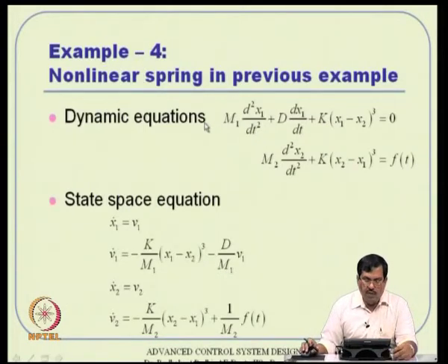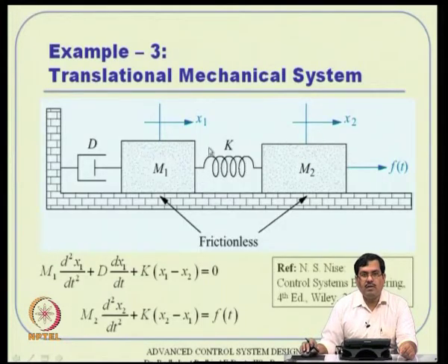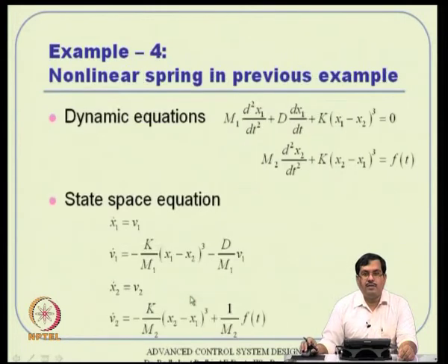Now, we will move on to nonlinear things. Because we know that state space representation can very well depict nonlinear systems as well. To begin with, I will assume the same previous example, however, the spring you see here is actually a nonlinear spring. Sometimes these springs are designed that way to speed up the response and things like that actually. There are some nice properties of the cubic spring equation. That means the force generated here is not a function of a linear expression like this, but a function of a cubic expression. Okay. So, this is what you see here.